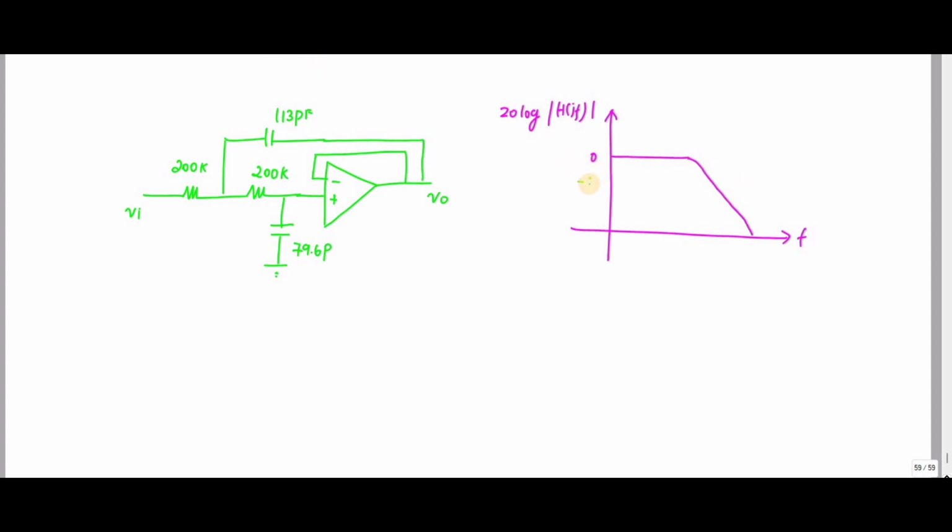So this is my minus 3 dB value, from which I can find the value of Fh. They asked about 1.2 Fh, and 1.2 Fh is nothing but minus 4.88 dB here. So this is nothing but 12 kilohertz. Okay. I hope you have understood this problem.